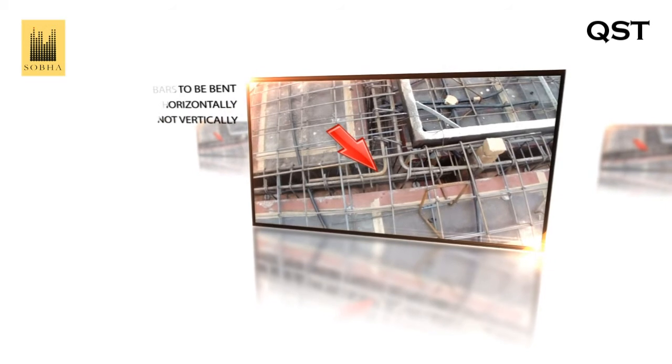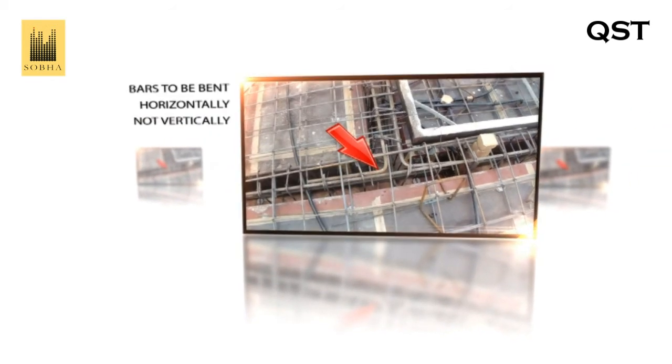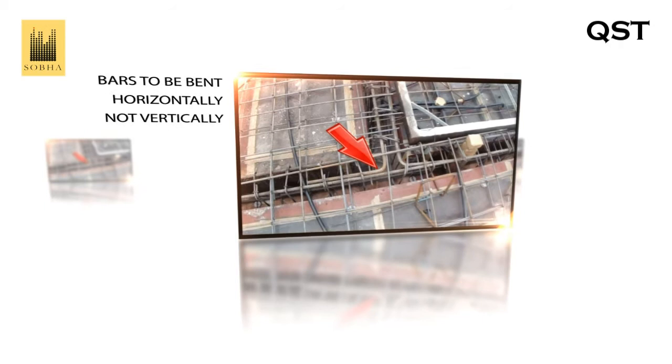In main beam and secondary beam junctions, the top rod of the secondary beam should be bent in L shape horizontally, not vertically, to transfer the load horizontally to the main beam member.